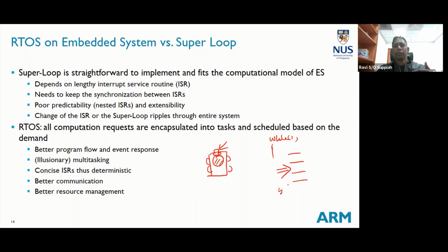Of course, you can use interrupts as much as you can, but there's also a limit to how many interrupts you have and how much you can do in your interrupt. Then it extends some more. Imagine that now I have a camera, and this camera data must be transmitted through Bluetooth to a laptop. So you have another activity that needs to run. This Bluetooth must also run together while I'm capturing data. So where do I insert that now? And if I now add 2 more IR sensors at the back, where do I add these?